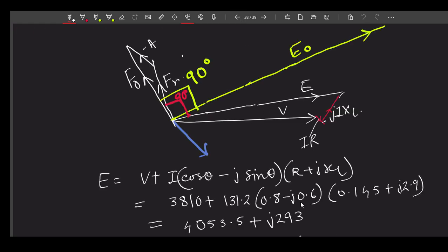Like here we have got, if IF is equal to 28.43, if we can figure out A, then although this is better suited for your cylindrical rotor machine, because one shortcoming with this diagram is that here I am assuming that armature reaction MMF is facing a constant path, which is actually not the case.